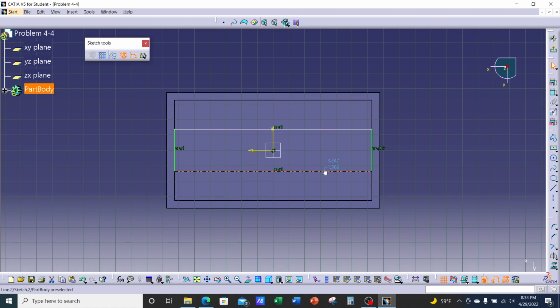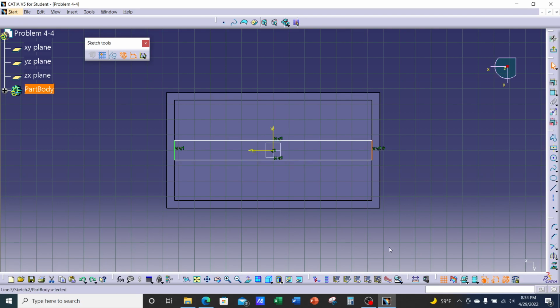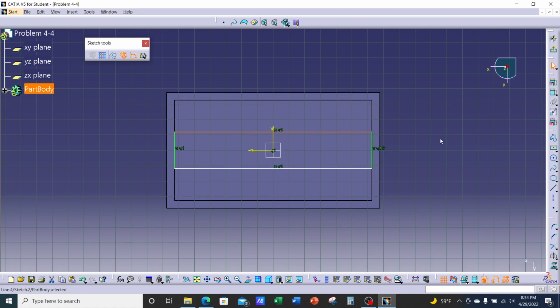Oh, didn't mean to do that. Let me hit undo, undo, undo. Somehow it undid my rectangle. Undo a few times. There it is. All right, so I moved so fast that it crossed things and it messed up my sketch. That's okay. So I'm going to add a dimension of 0.50. So that's the thickness. Let me click in space.